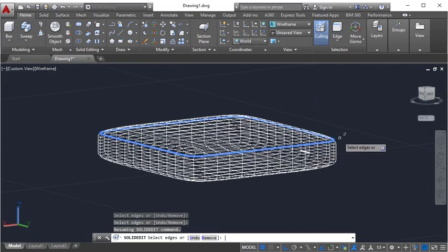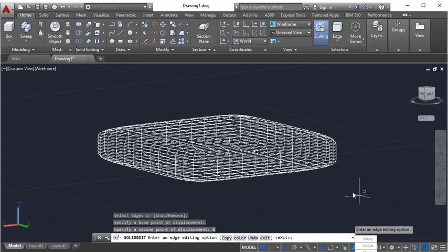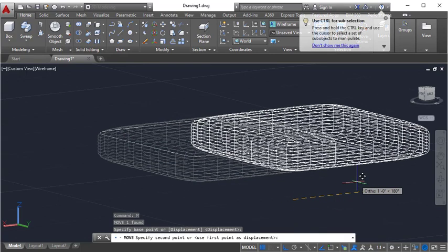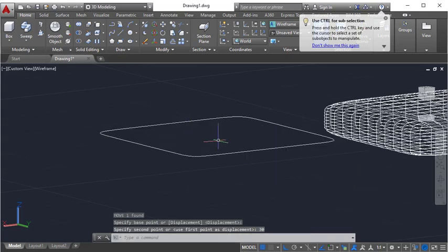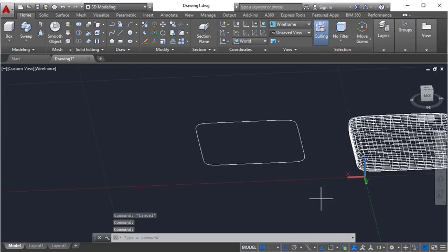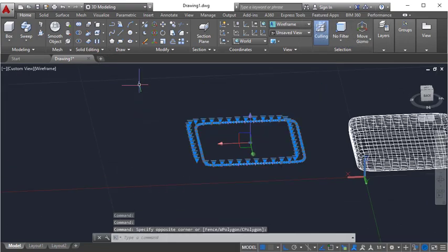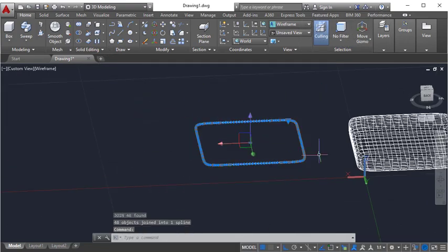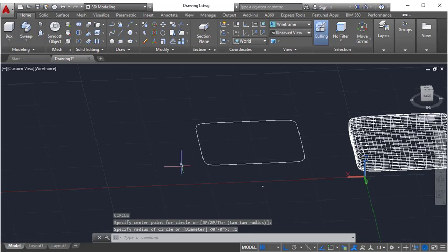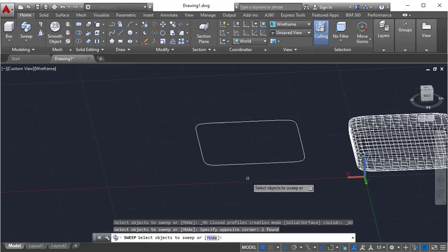After that, click enter and base point somewhere and show the direction at 0, enter. If you click like that, what happens here, you move it somewhere like 30 inches. All the edges will be copied and I can use a join command on this, J enter. See, the entire path will be picked, and I will use a circle like 0.1 radius, and I will use sweep